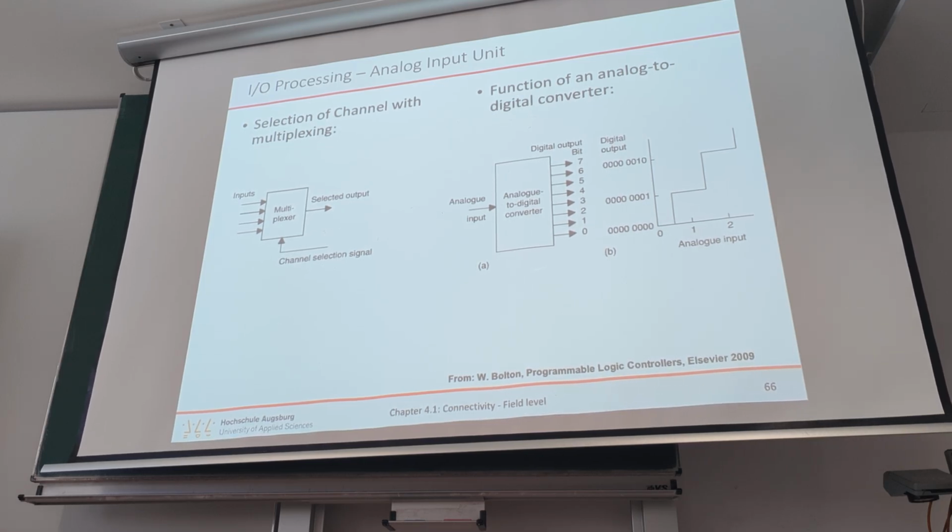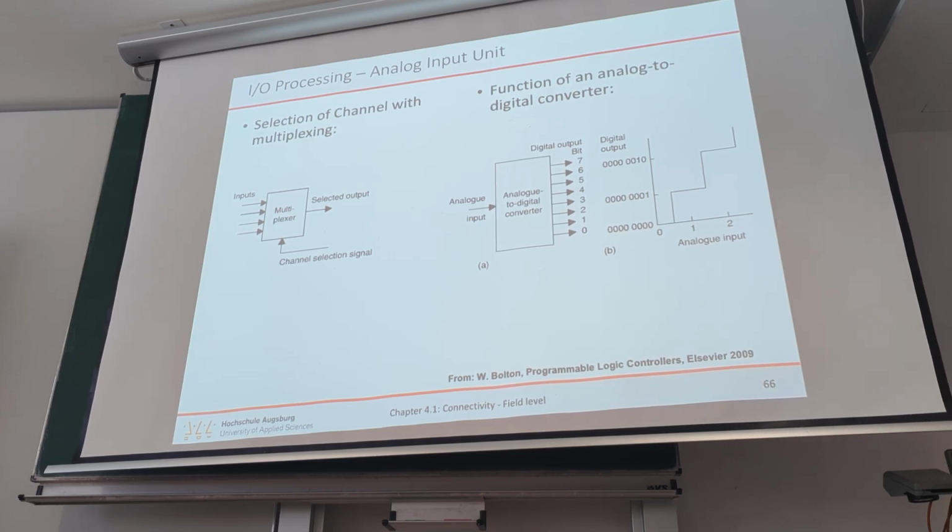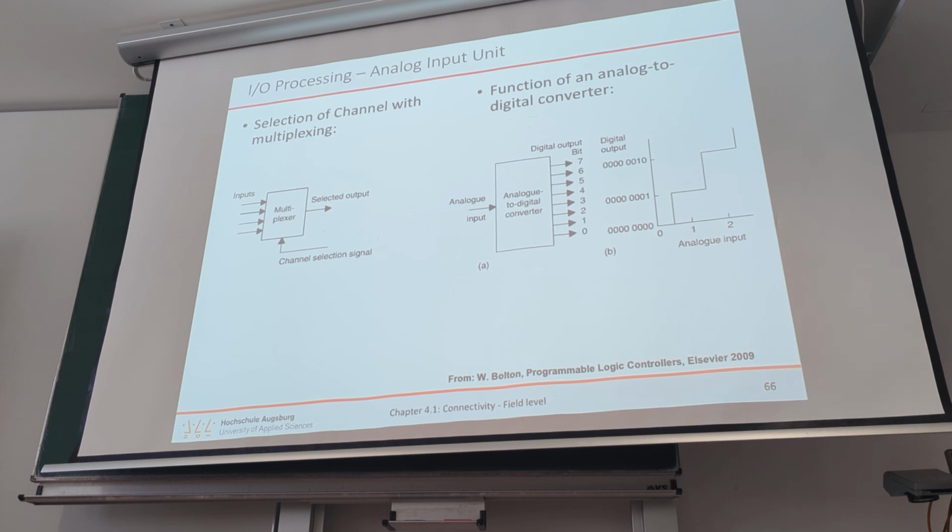And analog to digital conversion takes some time. There are different types of analog to digital converters. Usually, the fast ones tend to be less accurate, of course, and the slower ones can be more accurate, and if you want both, they get very expensive. That's also why, in a digital oscilloscope for example, it's one of the most expensive parts in the whole electronics.